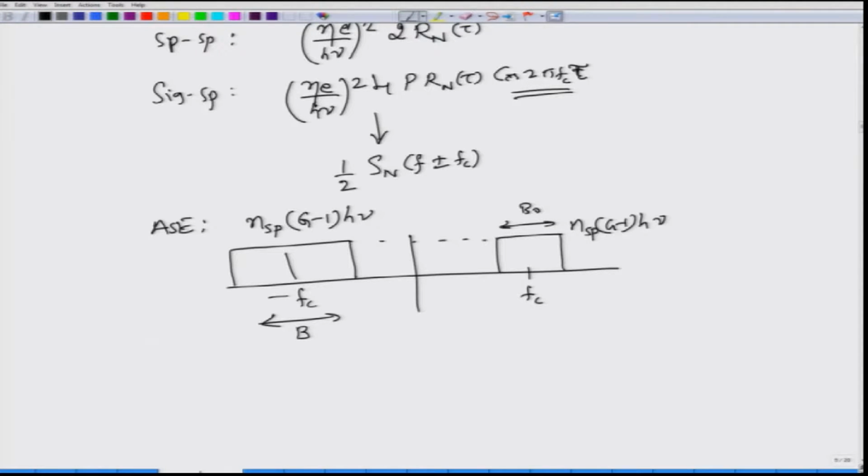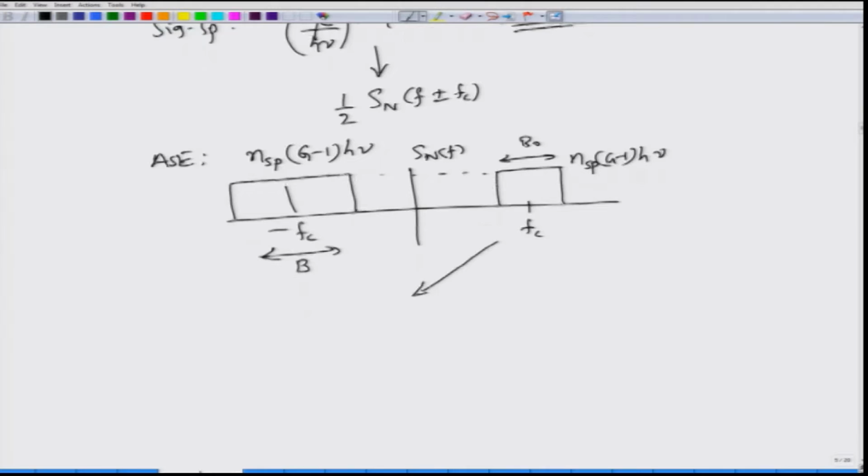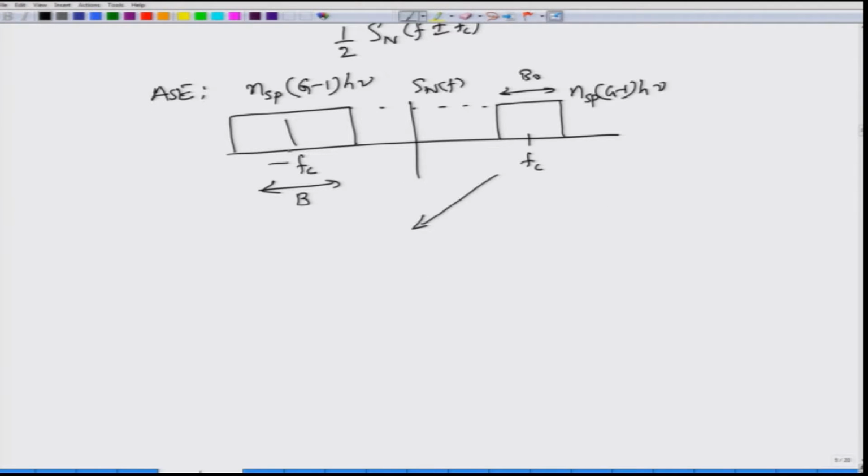This is the power spectral density of the noise, but when you shift them up to plus Fc and minus Fc, the one that is at minus Fc will be shifted to the center. So, if you now shift this one to Sn of f plus Fc, this term will be shifted down to the baseband level, this term will also be shifted to the baseband level, and one term will be thrown out into 2Fc and minus 2Fc. So, effectively this spectral density gets pushed into the lower frequency, 0 frequency,